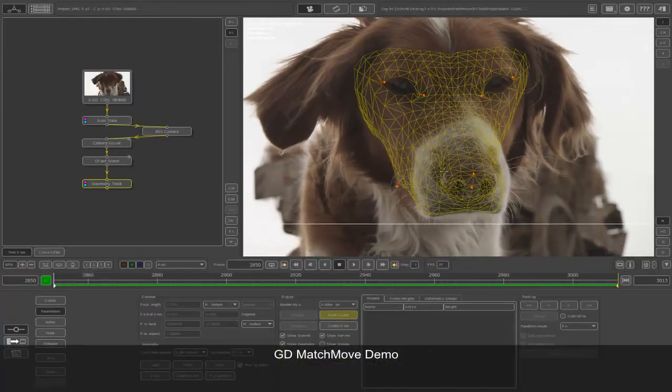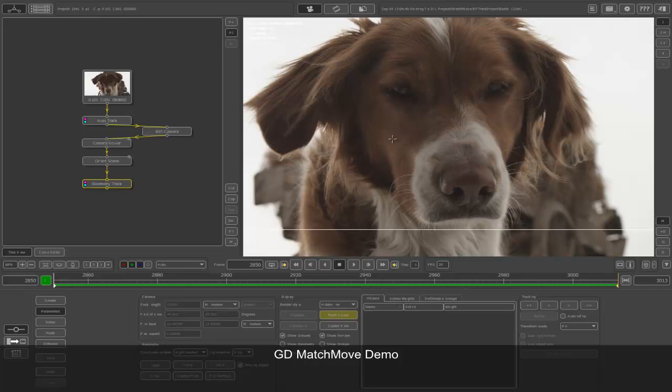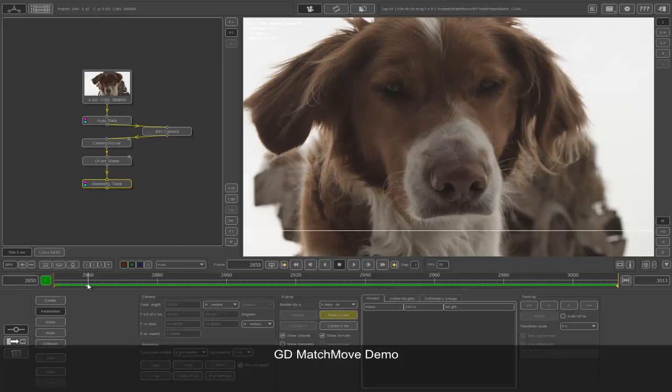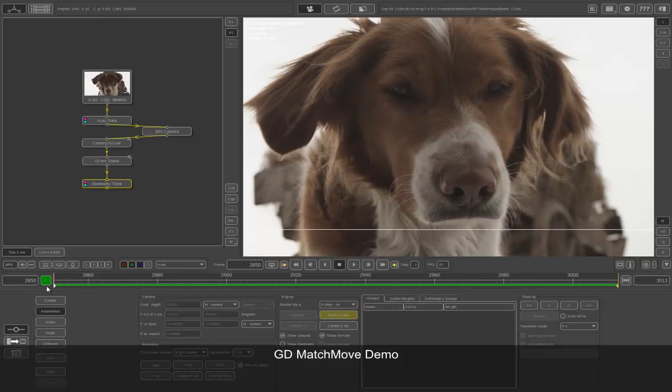So one major thing to understand is, let's say you are trying to track it, try not to track throughout and try to adjust all the keyframes, or try to create too many keyframes. Try to put in keyframes only at positions where the object actually changes its motion. If the current motion is about to change, put a keyframe in there, and that's more than sufficient.